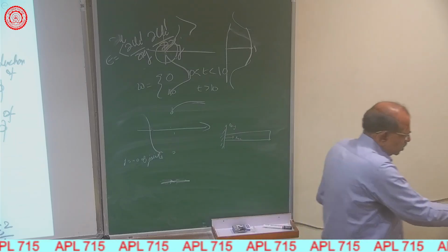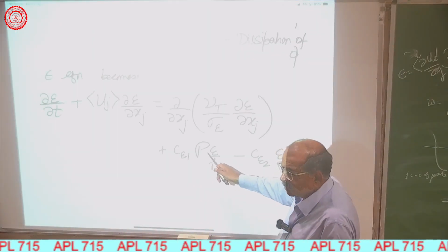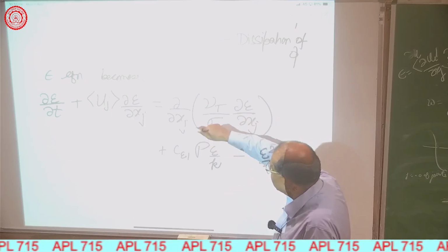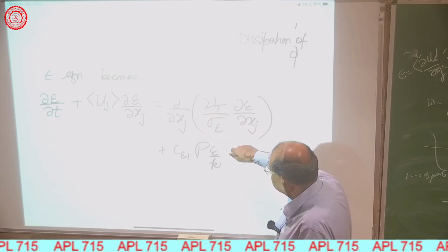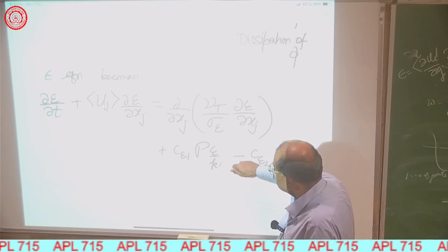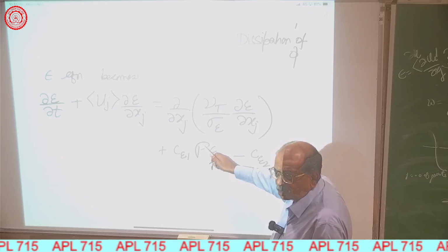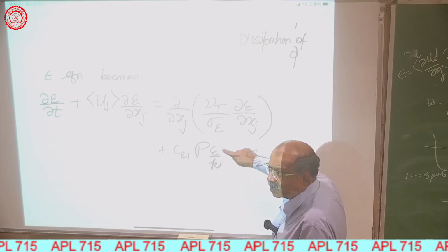Now in this equation you realize this P is still the turbulent production, but then in the equation we have d epsilon by dt. So the dimensional matching comes by putting this as epsilon; production is the same dimension as epsilon. So I have to put a d by dt. There is a t, and t is k upon epsilon.